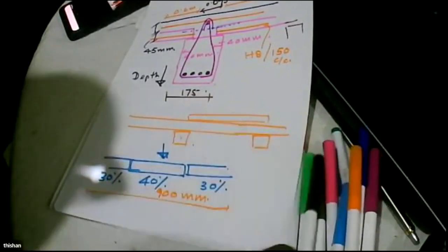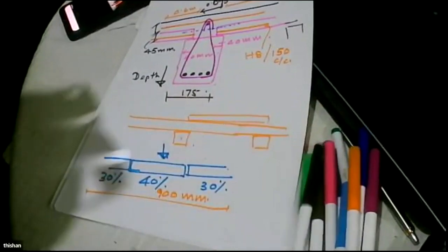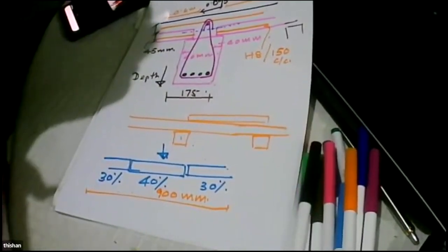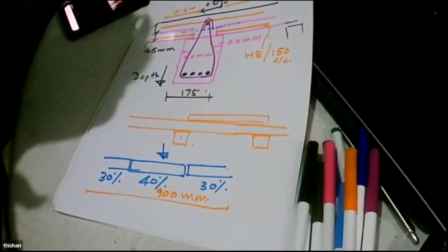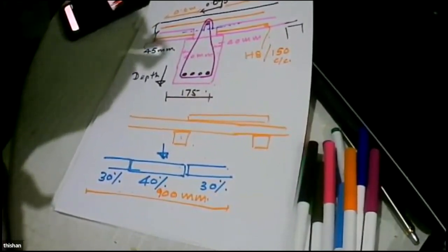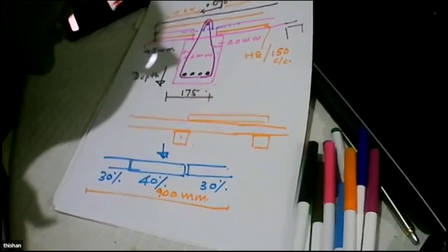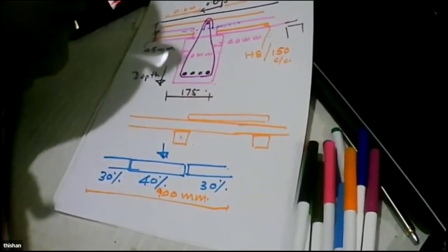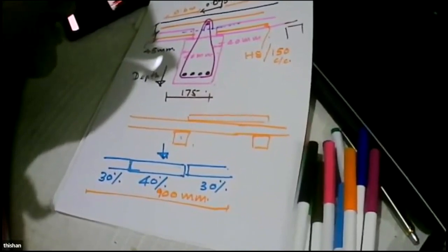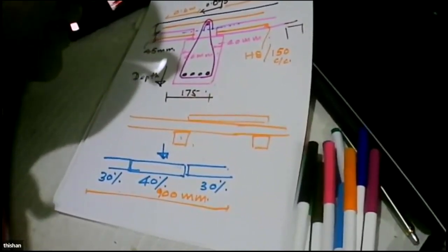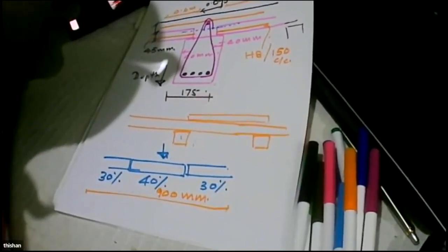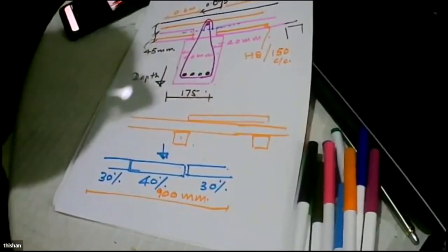Any other question? Yes, when reducing the slab thickness, there are other concerns like fire rating requirement and heat transfer. You don't have to worry about fire rating, because this is a slab, so half an hour fire rating is enough. Even if a slab has a local collapse, the whole building is not going to collapse. So what we need is about 30 minutes fire rating, and 30 minutes fire rating can be easily provided by these slabs. And if you have any issue with fire rating, then what you have to do is apply a seal. Sealing will look after that.